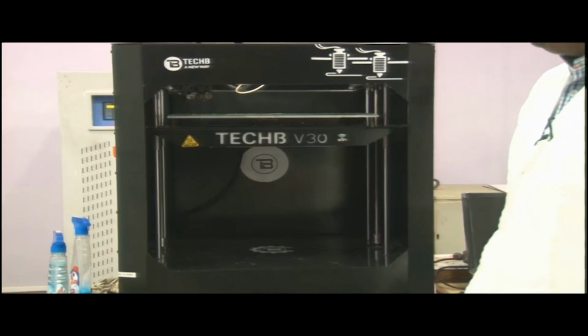The precision and smoothness of the printed models are also influenced by other factors, such as the bonding force between the layers, whether it is lower or adequate, and the weight of the upper layers that squeeze upon the lower layers. There can also be printing defects like warping, misalignment, shrinking and shifting of layers, all those things could be there.